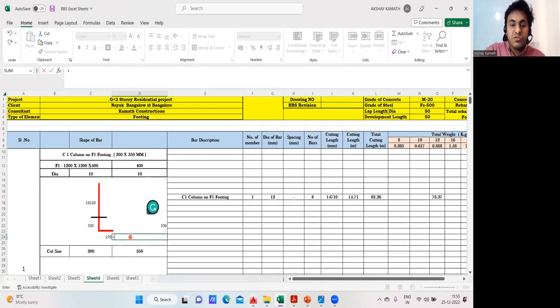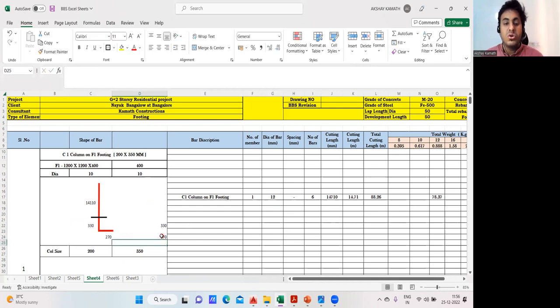Okay. Plus 50 is here, development length, multiplied by the column diameter I'm doing. So column diameter I have to take as 12. Getting my point, no? So fine. 50 into diameter of the bar minus this straight length, and close the bracket. Enter. How much did I get? 270. Finish. Pretty simple. So this is 270 and this is 330.